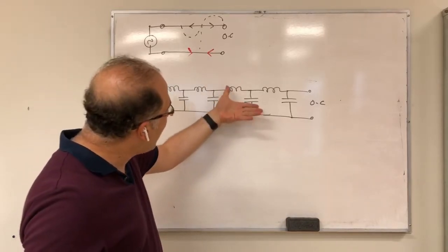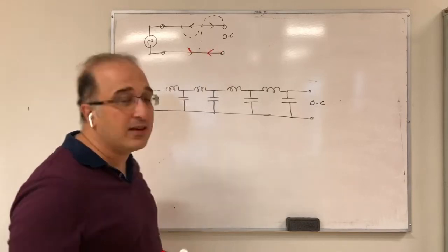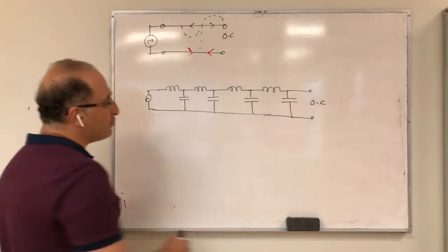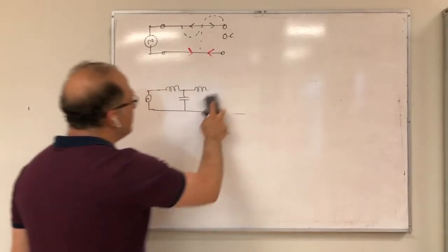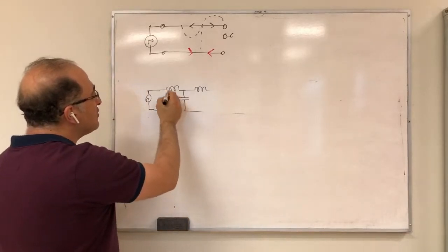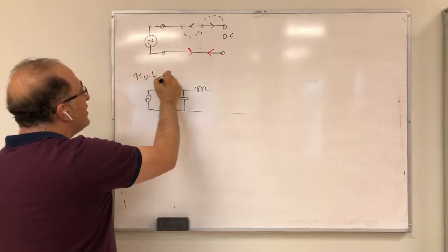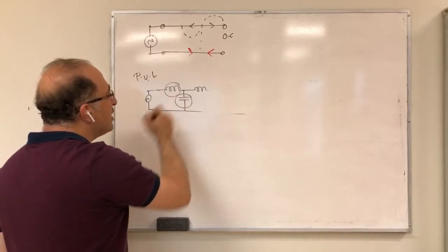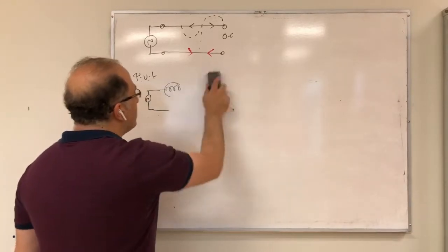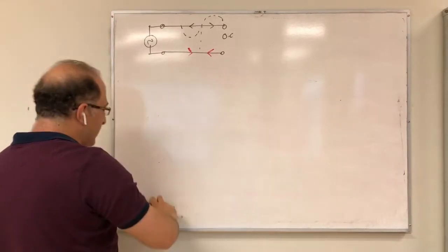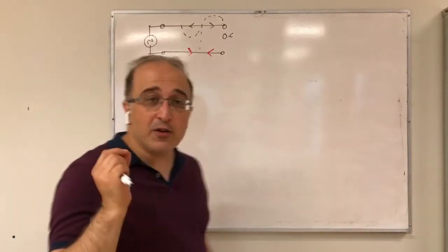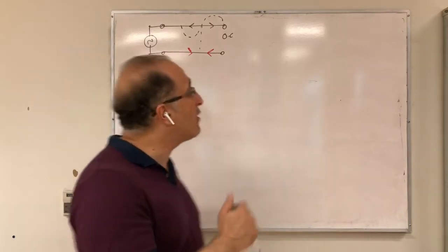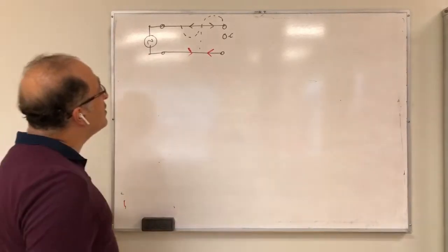If you have this picture when you are thinking about this transmission line, then it makes much better sense. If you remember from your transmission line course, we call these PUL inductance and capacitance: per unit length inductance and per unit length capacitance. Then we use these to find the characteristic impedance of the transmission line, which is often 50 ohm in our applications.